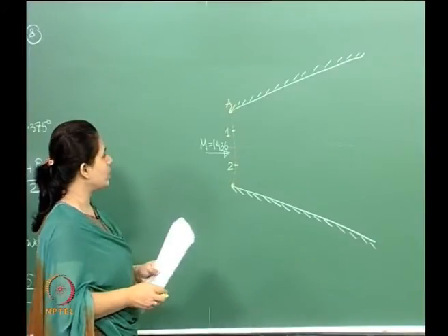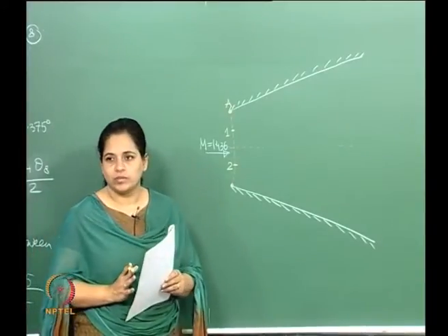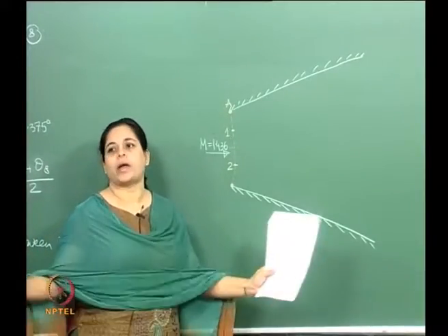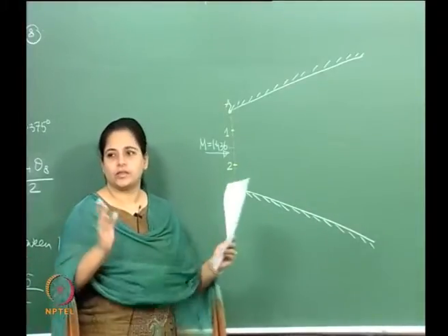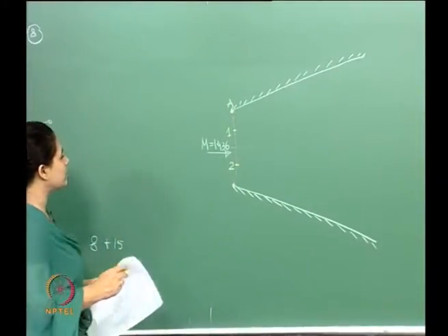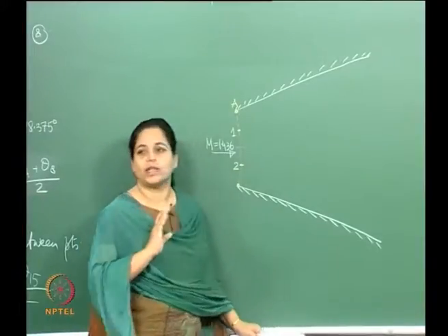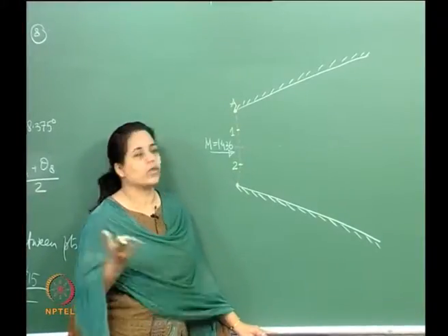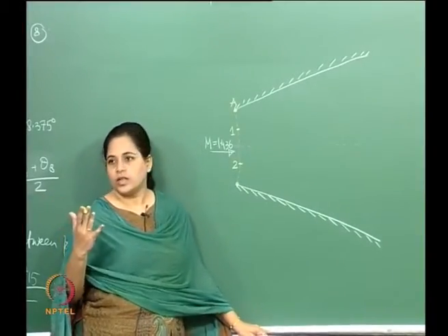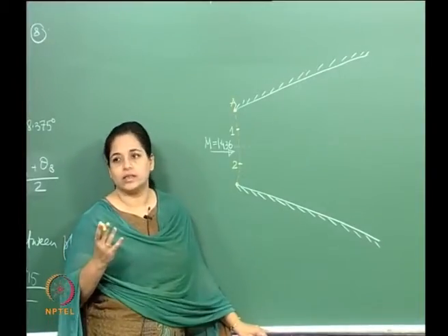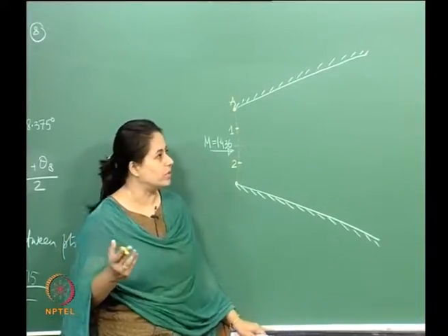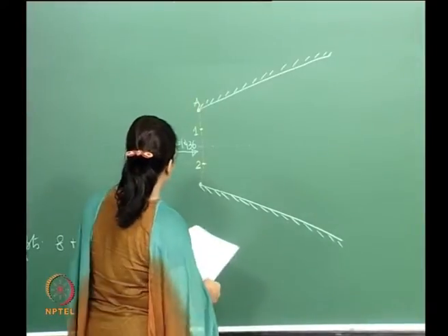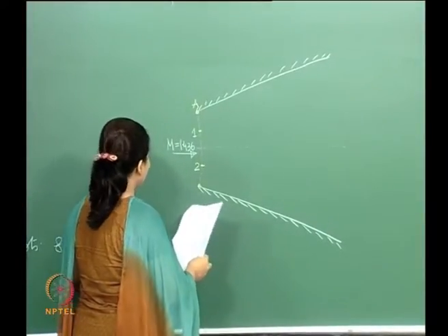Now what is happening is the flow is expanding, isn't it? So it is an expansion fan. We will draw this expansion fan, and unlike the minimum length nozzle, now it can expand over a length. It is just a channel, so it is not necessarily a centered expansion fan.